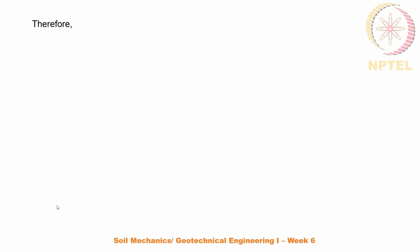Now, we have shear strength S is equal to sigma tan phi. So, sigma is equal to 2.5 into 17.2, that is 2.5 gamma d, plus 5 minus 2.5, that is the remaining 2.5 depth of saturated soil, into gamma saturated, that is 20.783.